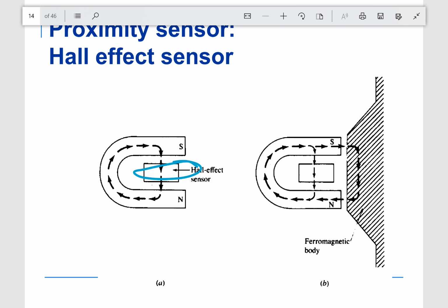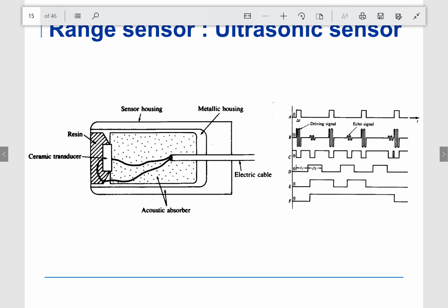This is a range finder. This is an ultrasonic. The concept is relatively simple. We send out a pulse right here. Here's our pulse, and we look at when the pulse returns. It's very similar to radar. Now the whole idea when we look at an ultrasonic sensor is that here's my, and I'm going to call this my sensor. Here's my object. We bounce this off, and it comes back.